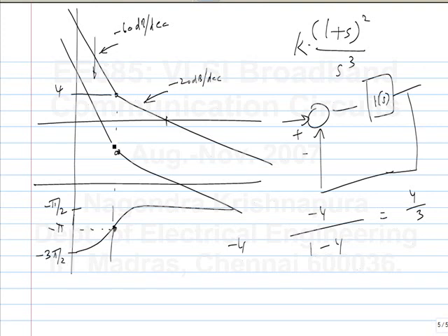Normally, this kind of phase margin was useful especially in the beginning of negative feedback, because you had only simple systems and conditional stability was not very well understood. As you went on increasing the gain inside the loop, it would be stable for some values of gain and then become unstable. But with conditionally stable systems, for very small values of gain, for k equal to 0, which means there is no negative feedback loop, obviously it is stable.